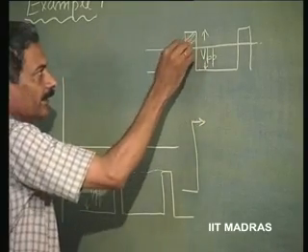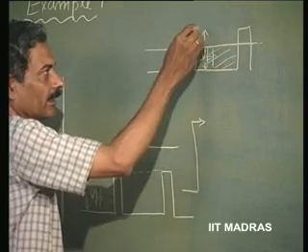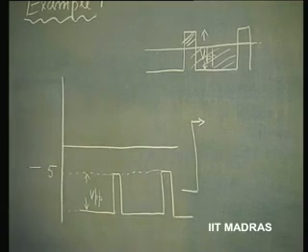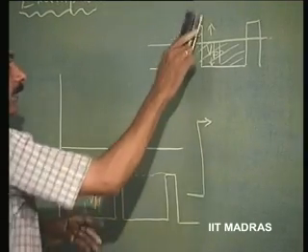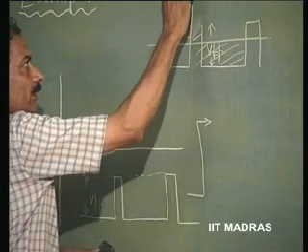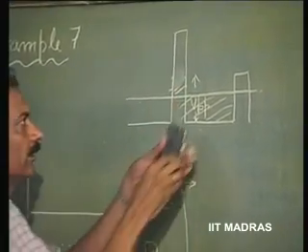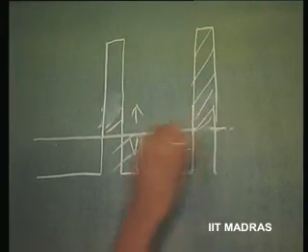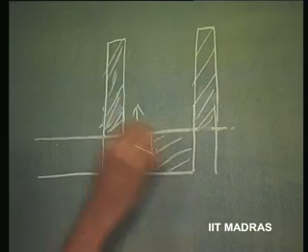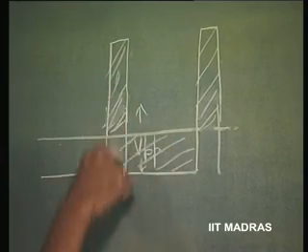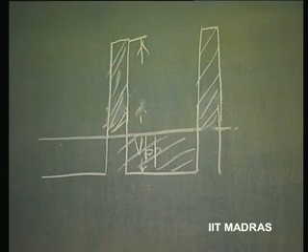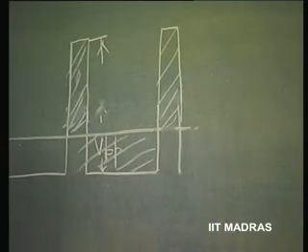The only thing that is required is AC, there is no DC in it, and let us say this area and this area are equal. So actually I should have drawn it more carefully. If you want this area to be equal, it has to go pretty high here. So, let us say the positive area and negative area are equal, so that this is AC with zero DC. So peak to peak is extending all the way from here to here. This has to be clamped down to this. So what circuit do I apply this voltage to in order to get this output?